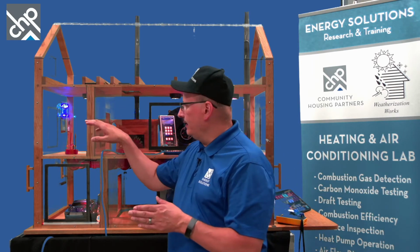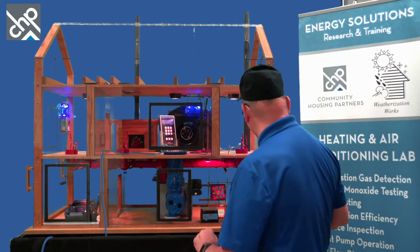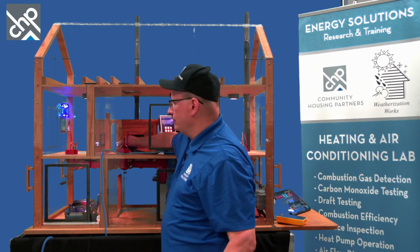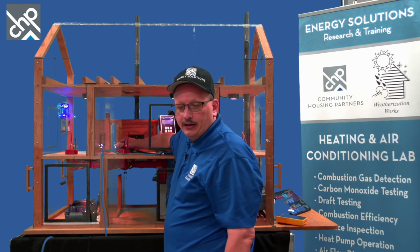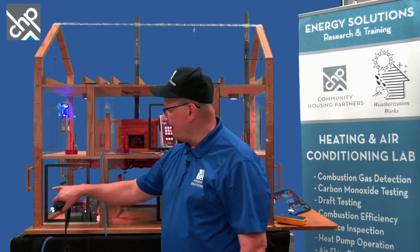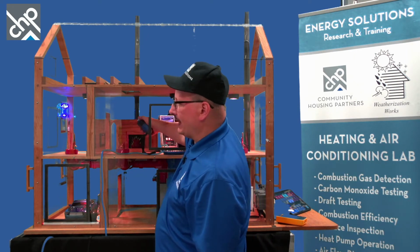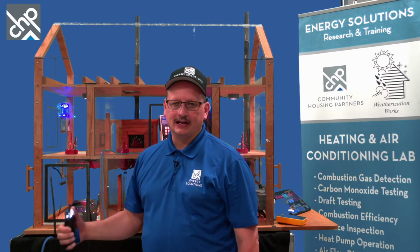So in this case, I've got the bathroom door, bedroom door, and the basement door all closed. If I wanted to check those doors, I'm not going to zoom in on it, but you can see what you would do if you were in the house. You'd be standing at that door, and you would puff the smoke. If it goes under the door, in this case for the bathroom area, that would tell me that exhaust is stronger than the supply, because I have a supply and an exhaust in that room. If I puff smoke and it blows back out toward me, that means the supply is stronger than the exhaust, and if I open the door, it would give makeup air to my CAZ.